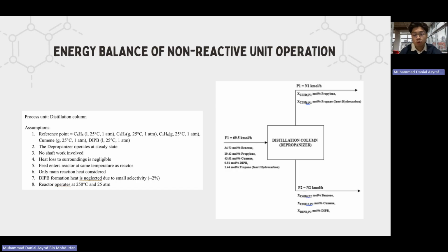The system is assumed to operate at steady state, meaning that there is no accumulation of energy within the unit over time. In addition, shaft work is assumed to be zero, since the distillation column does not contain any mechanical service such as turbines or compressors that perform work on the system. Heat loss to surroundings is also negligible, allowing us to assume that the heat transfer only occurs within the process streams.